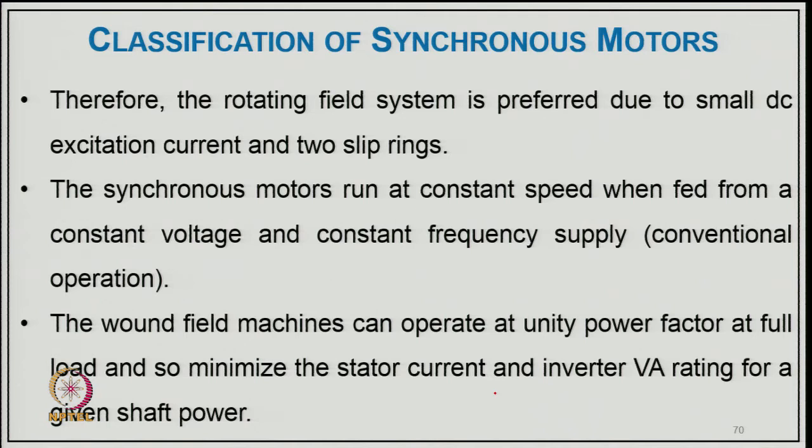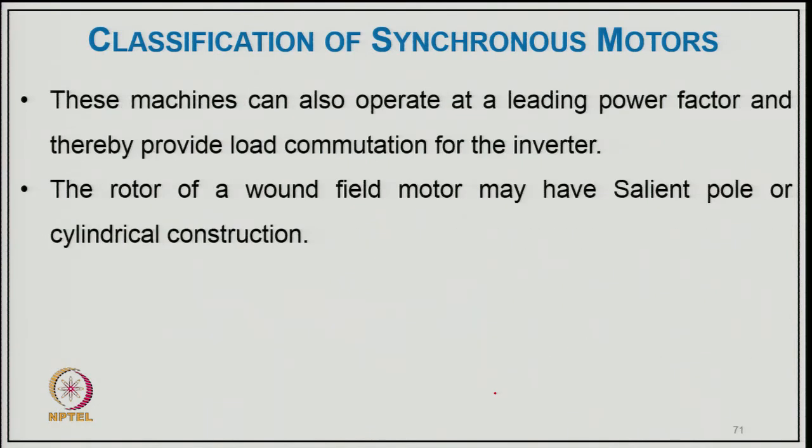So, synchronous motors run at constant speed when fed from a constant voltage and constant frequency supply. Especially conventional wound field machines can operate at unity power factor at full load, and so minimize the stator current and inverter VA rating for the given shaft power. These machines can also operate at a leading power factor and thereby provide load compensation for the inverter, and the rotor of the wound rotor field motor may have salient pole or cylindrical construction depending upon the speed of operation.